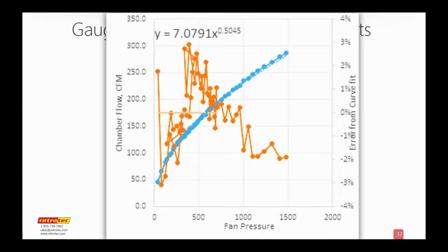And on this particular range, I think we've probably taken 400 or 500 data points, to get a really good idea as to exactly how this particular range responds at different pressures and also different back pressures. So, we'll test a device which could be a duct tester or a blower door. We'll test those devices at a whole range of back pressures to see if, let's say, for example, we're testing at 25 pascals or 250 pascals, if it will make a difference.